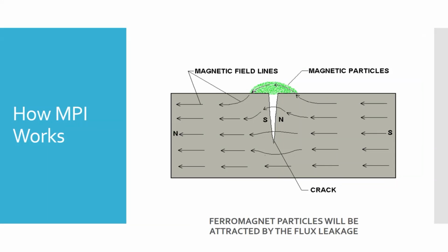And you can see where more particles are being held on the part versus areas that have less, where it doesn't glow as much. So that part we looked at initially, those cracks held a lot of those fluorescent particles. The rough surface held some, but there was an obvious contrast there between where the cracks were and where the cracks were not.